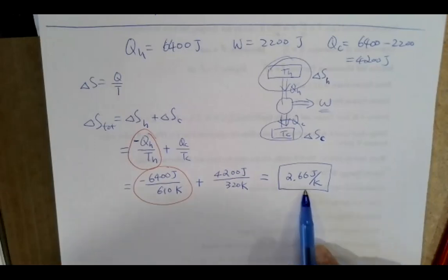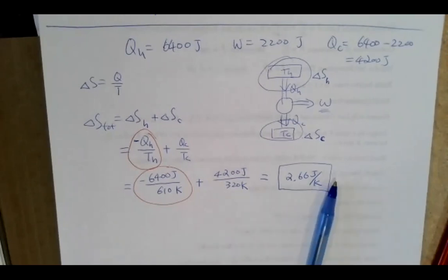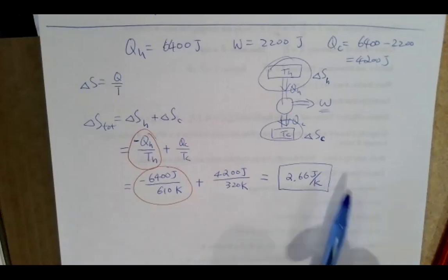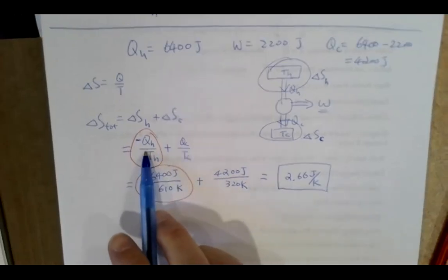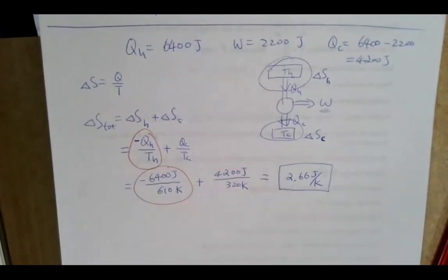So this is the total entropy change, the number. It actually means the disorderness. So the disorderness of the system will increase. So in reality, the entropy change will not be negative. Okay, just keep that in mind, if you get total entropy change on the system. If you are looking at individual ones, they might be negative, but the total should be positive or at most zero. Zero refers to the ideal situation, which actually in reality never happens, but in theory it could be.